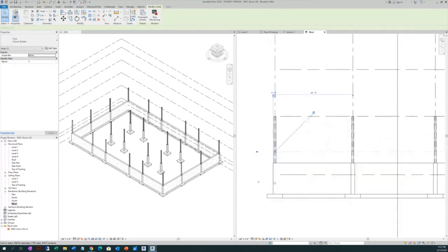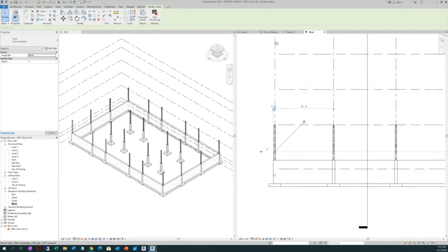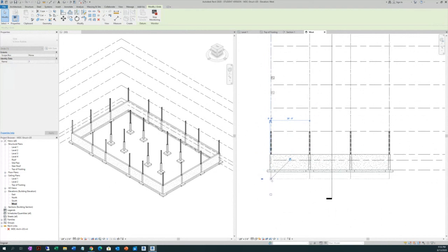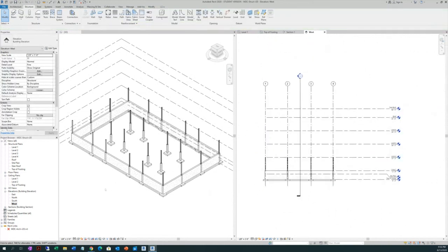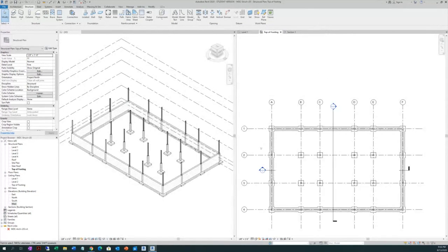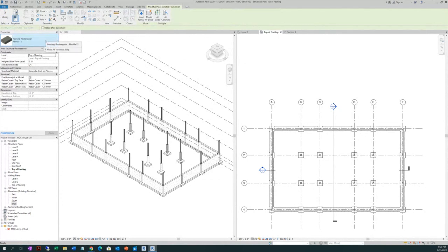and then you notice that you have the handles here at the end, the bubble, a little circle. You drag it down. I did it. Then you should notice that on your footing plan. I want you to make sure that you see it. You got it? Yes, I got it. Okay, now I want you to go in the structural, select the isolated. Okay? Yes, I did it. Now I want you to make it 48 by 48 by 12.